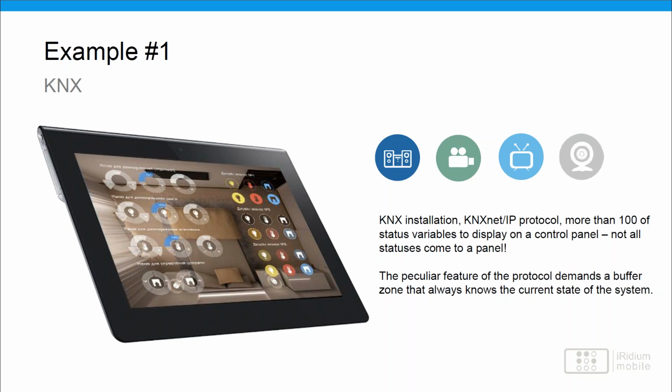You may know that if you are sending to the KNX bus more than 100 or 200 requests for reading the status of KNX installations, you may not receive all the statuses in your application, in your visual project. For your customer, it looks like some lights are on, but some lights are not on, though I know it is on.